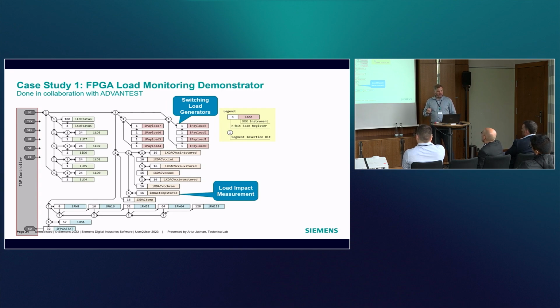instrumentation. While you execute the test, it may be executed correctly, so you get your pass results. But while you do measurements at the same time, like measuring temperature and measuring voltage, you may see abnormal actual behavior during the test, and that may be an indicator of some faults that are hidden inside, which were not discovered by just functional tests. So, some sort of indirect discovery of faults.